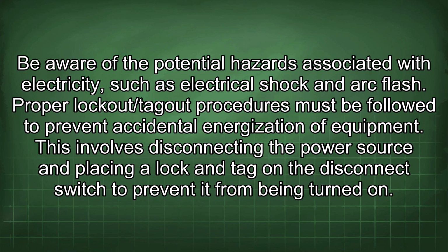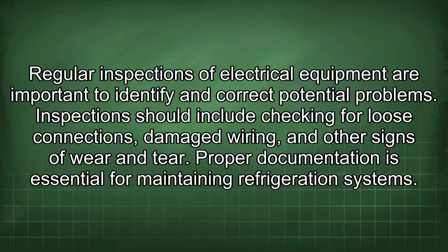Proper lockout/tagout procedures must be followed to prevent accidental energization of equipment. This involves disconnecting the power source and placing a lock and tag on the disconnect switch to prevent it from being turned on. Regular inspections of electrical equipment are important to identify and correct potential problems.